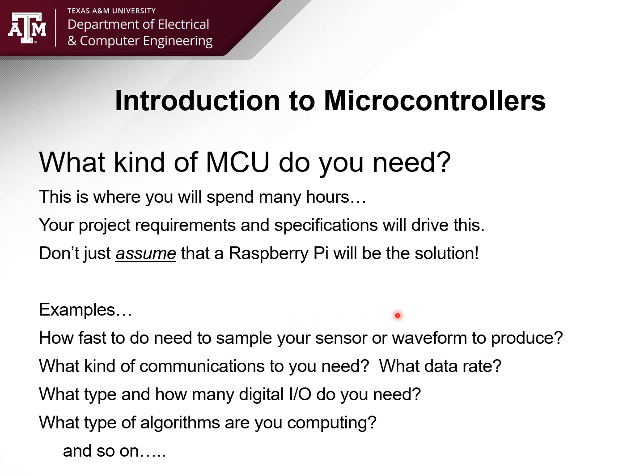You have to ask yourself, what are you doing with your microcontroller? Am I interfacing with an A to D converter? Am I trying to get sensor data out of that microcontroller or into that microcontroller from something? If it's really slow, like temperature or pressure, where the changes are, at best, slow, 10 hertz, 5 hertz, then probably almost anything you throw at it will work fine.